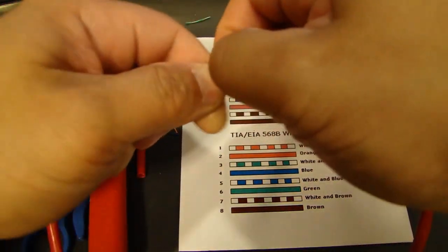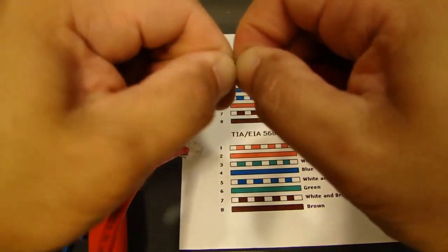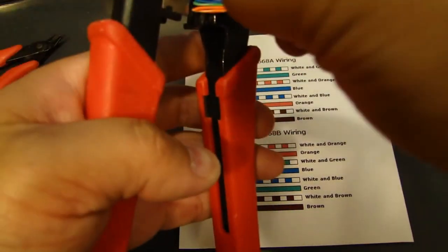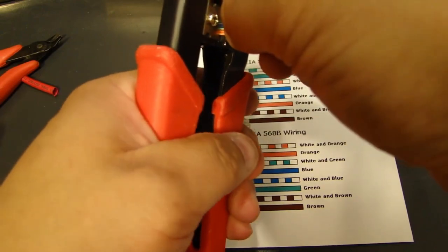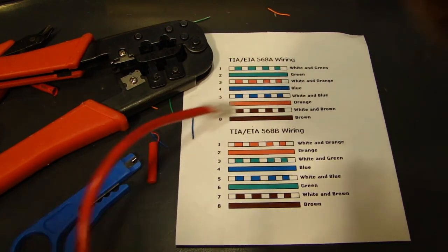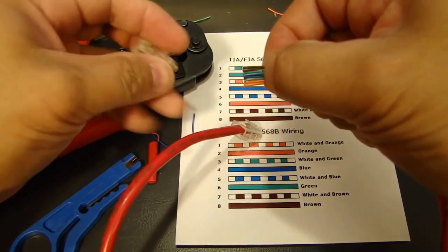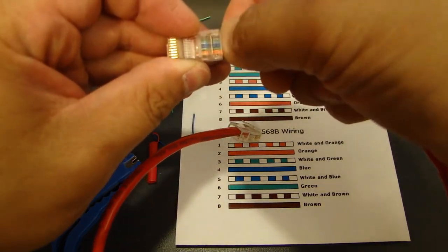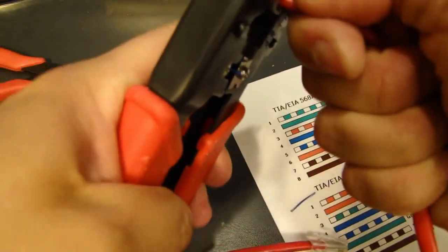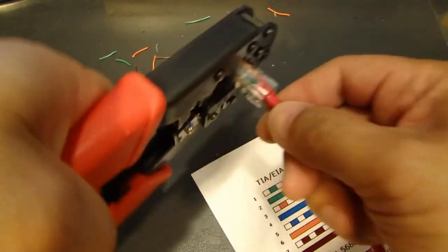Again, I just like to work it this direction, so I like to sometimes squeeze it and twist it so I make it all flat. Do that. So go ahead and cut this. So make sure you hold it down carefully. So this is gonna slowly feed into here. Feed this wire in here on a crimper. Put it on a crimper and crimp it down.